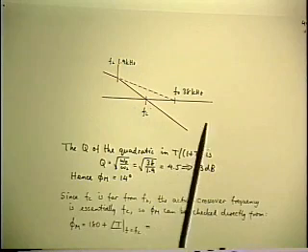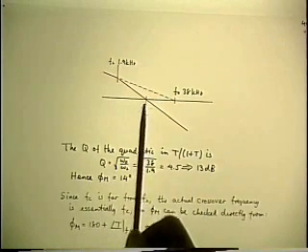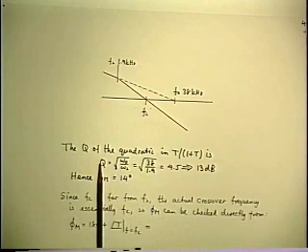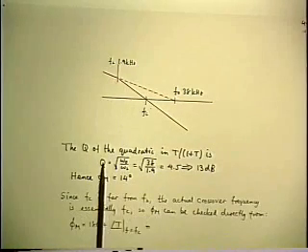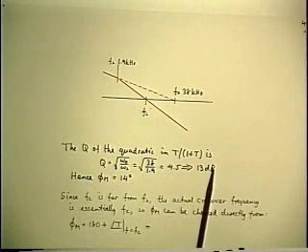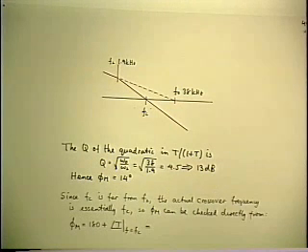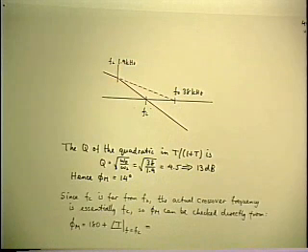which is still part of that general case that we solved earlier on, except that the closed loop discrepancy factor now is still a quadratic, but it has a high value of Q, because the second pole is now at a much lower frequency. And when you plug the numbers in, the Q is 4.5, 13 dB. And that corresponds, of course, to a very small phase margin, only 14 degrees.